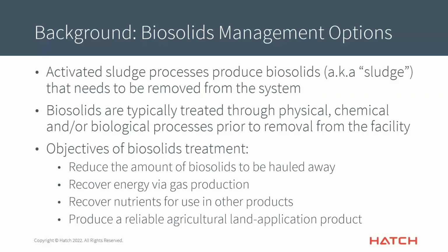Those being that you, first of all, want to be able to reduce the amount of biosolids that you are going to be hauling away from your facility. That is due to the cost. You want to get as much of the water out of it as you can and reduce the amount of actual solids that are there to be hauled away, to get the VSS reduction as much as you can. By doing that in an anaerobic context, you can generate some gas. So that might be one of your objectives as well, to capture that gas and use it to do heating or generate electricity or what have you.